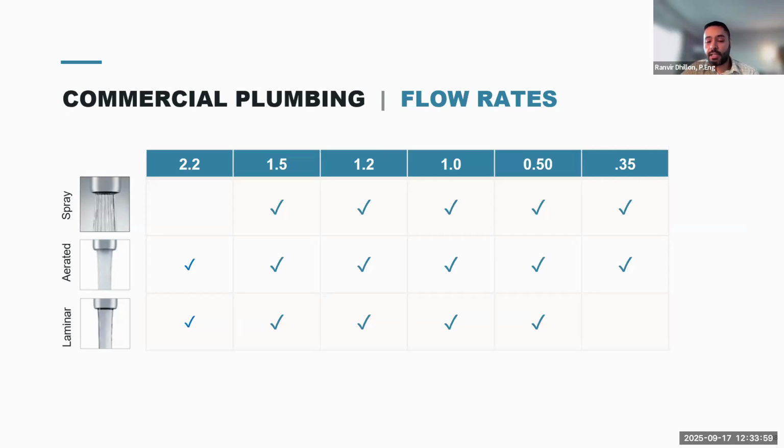For healthcare applications, more water flow is needed to meet surgical scrub requirements, and the aerated spray can't be used. Although aerated is the most popular type used elsewhere because it makes streams feel stronger by mixing it with air, it can't be used in healthcare applications because introducing air into the faucet stream can potentially introduce airborne pathogens into the water. The type of aerator can help you also meet your goals in other areas.